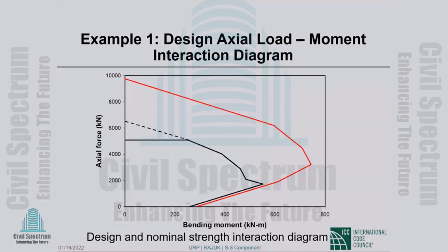But let us say you place the additional bar 8 inches from the corner bar. Then you have more than 6 inches of clear spacing between this bar and the corner bar. Now these additional bars will require a cross tie. So that's how it works.